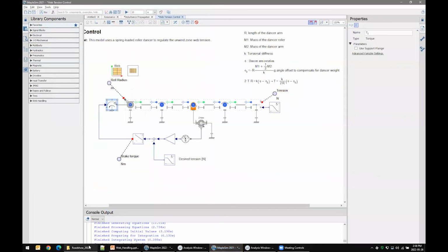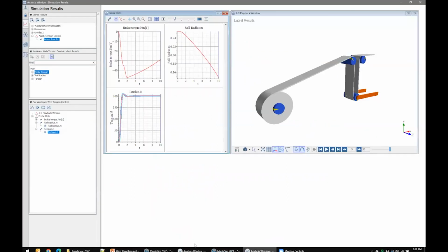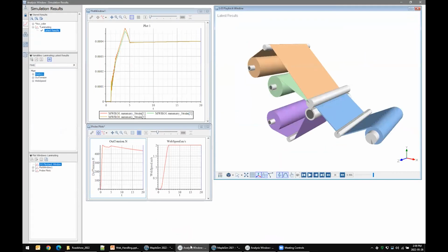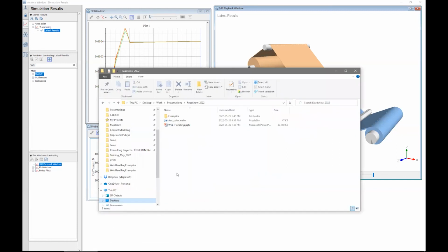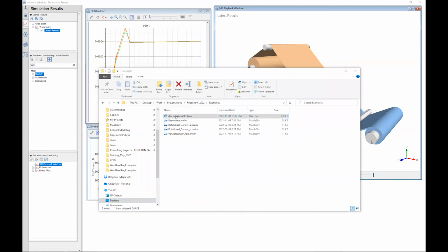The only other thing I wanted to include is that once we create these models in MapleSim, another main use case, other than just investigating and designing, would be virtual commissioning. For that, we can export our models in a variety of different ways so that you can use your automation tool to have it interact with your PLC program and make sure that your controller is doing what it's supposed to do. One of the ways of export would be to export a model as an FMU.